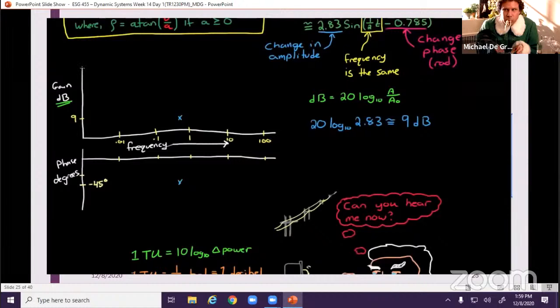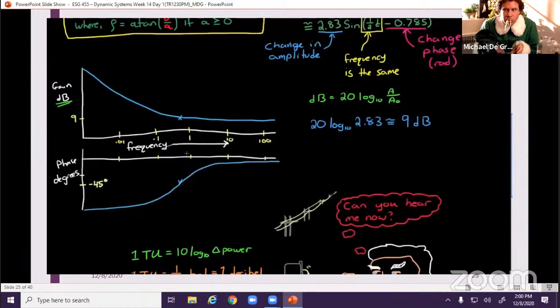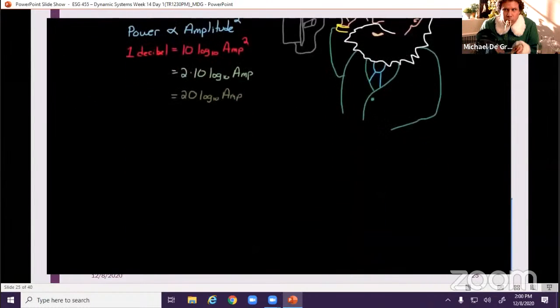So instead of running through the example above an infinite number of times, each at a different frequency, we could have just set it to a variable like omega and solved the system for any frequency. So if we had done that and we had a lot of time, we could have plotted a gain and phase plot that looks something like this for our particular system. And with the exception of being time-consuming, for this simple example, solving the response to the sine wave input was relatively straightforward. Well, except for having to remember that crazy trigonometric identity from earlier.